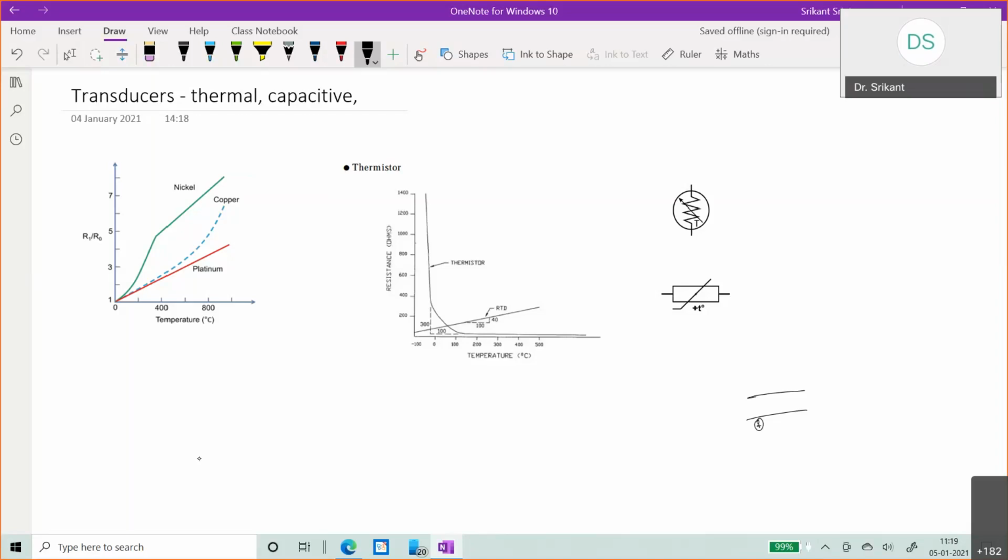So if you don't have many carriers, then as you supply heat to the system, you generate carriers. So you get electrons and then you get holes. So as you apply heat to the system, you can generate a greater number of carriers. And as a consequence, you can increase the conductivity of the material.